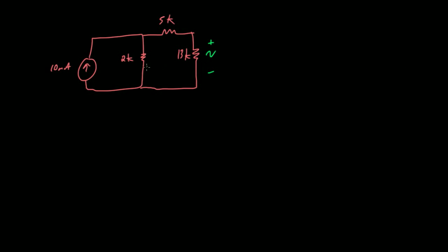The first step in nodal analysis that we've talked about, and maybe I might be getting this a little bit wrong since it was a while since I did those nodal analysis videos, is to identify the unknown nodal voltages, to identify all the different nodes in the circuit, all the different places where you can have different voltages. So let's start out here. This is clearly one node, so everything that I'm shading in here has the same voltage. Let's call that V1.